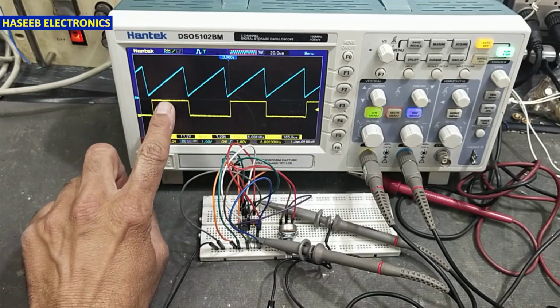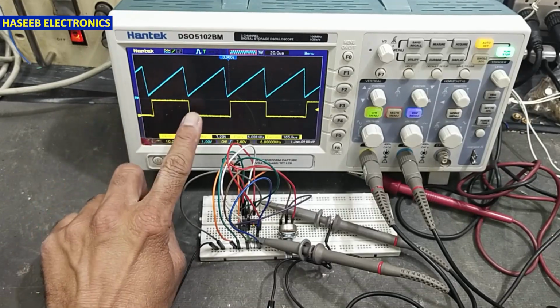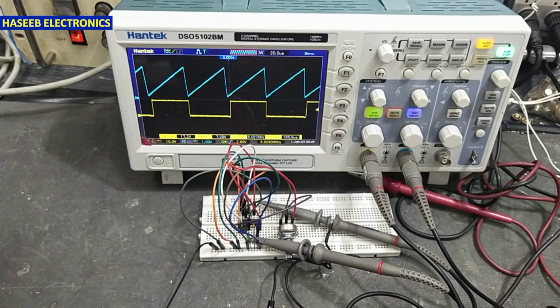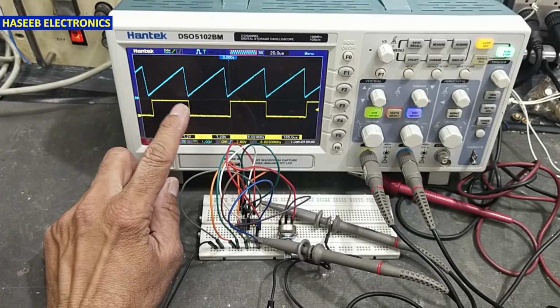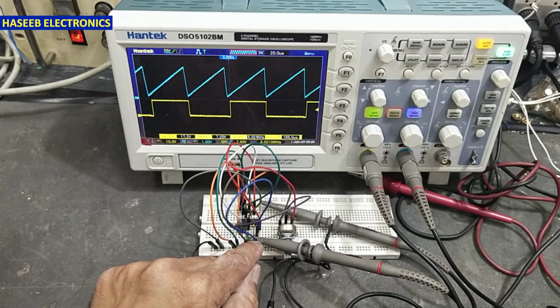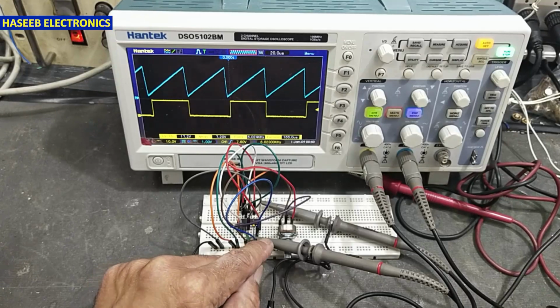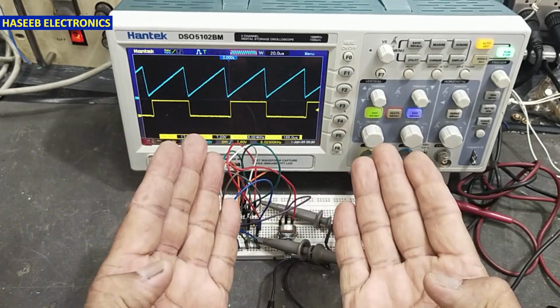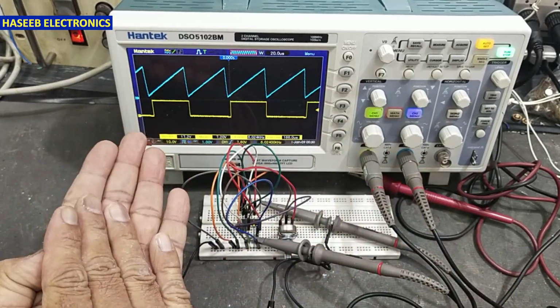One cycle will switch high for one channel. At the same time, the second channel will remain off. It will cause the output frequency to be divided by 2. Our RT/CT is programmed at 12 kilohertz, and we are receiving an output frequency of 6 kilohertz: 6 kilohertz at one channel, 6 kilohertz at the second channel.